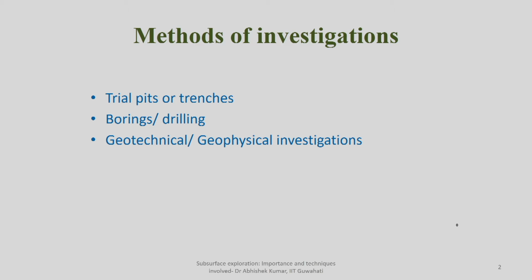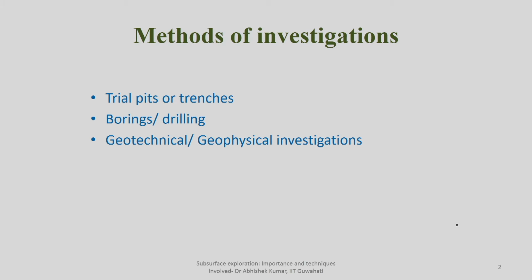You go to the site and collect some samples that give you an idea of what kind of soil is there. Then we go for detailed investigation by means of drilling or boring at the site, depending upon whether you are drilling in soil or in rocks. So, what are the different kinds of drilling and boring available?